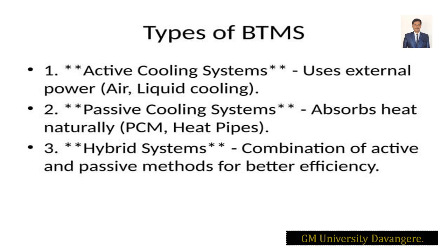Alright, so let us see what the types of BTMS are, right? In a battery thermal management system, there are types of cooling. One is active cooling, and there is passive cooling, right? In active cooling, we are using external power, right? That will be applied directly to the heating area. It may be air cooling or it may be liquid cooling, right?